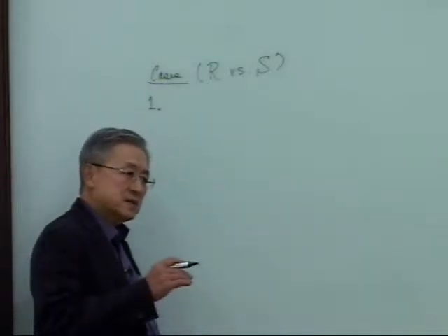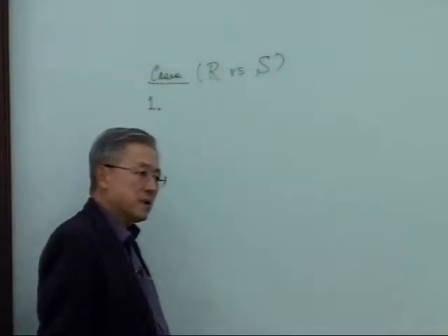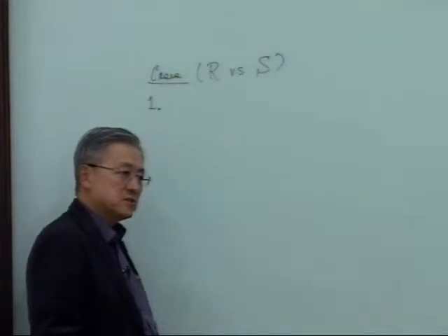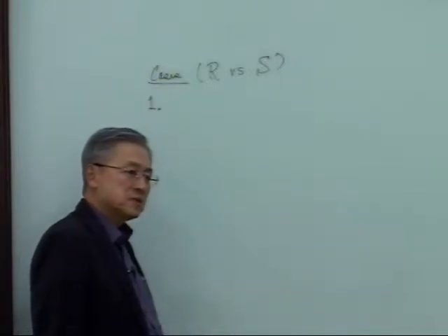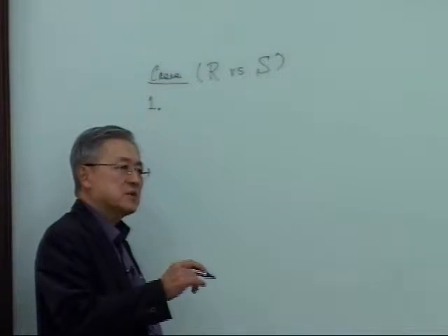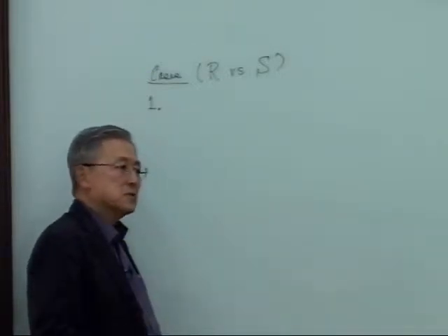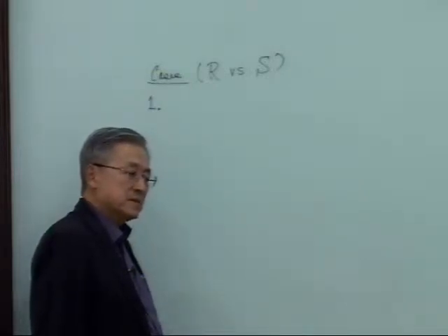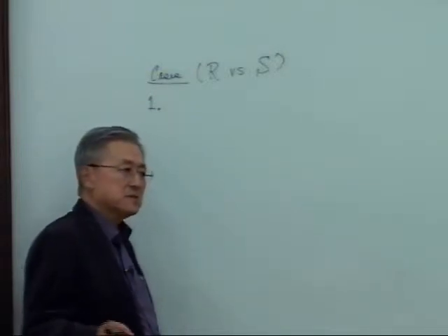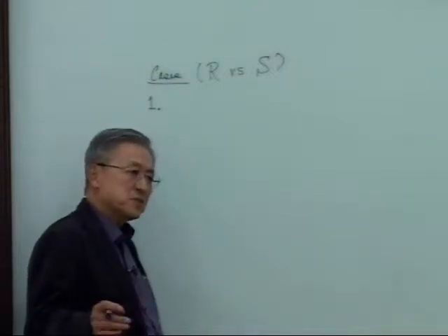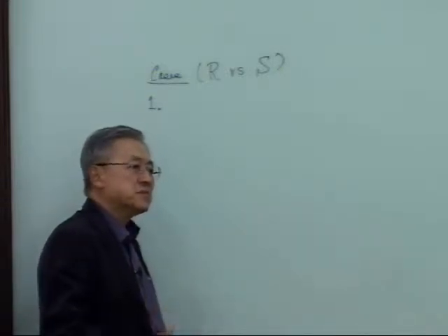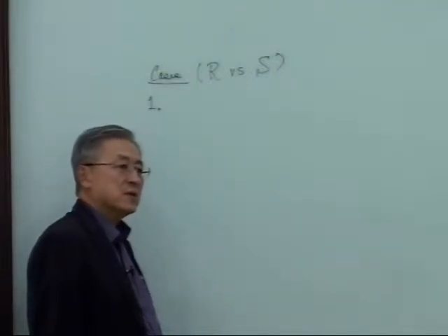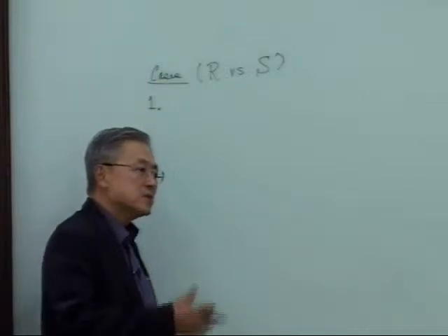Because, for example, for the buckling problem, the loading and resistance relation, or loading or stress relation, buckling stresses, is nonlinear. So for safety reasons, you apply the safety factor to the actual loading to get the design loading. Then the basic question, as Elishakoff clearly indicated, is the main reason I picked this up. I'm going to cover a few chapters on this. How does the safety factor relate to structural reliability?